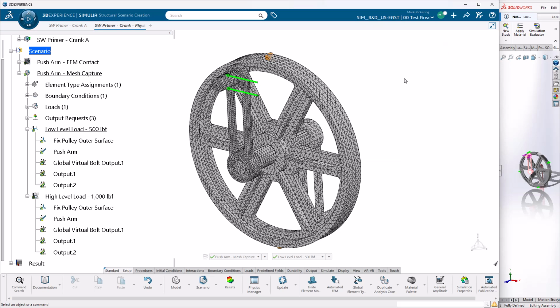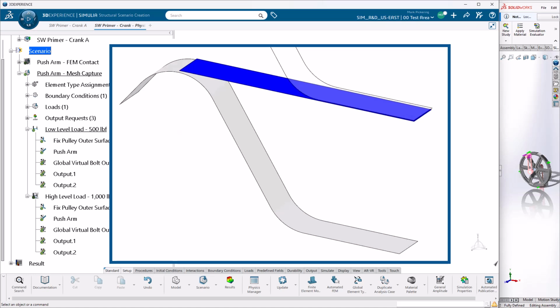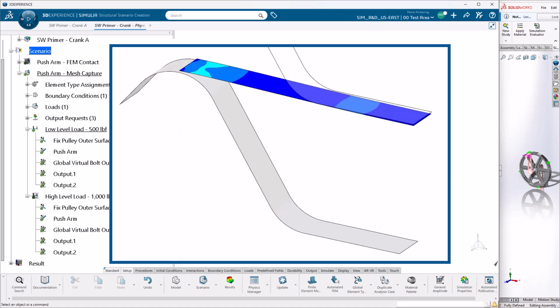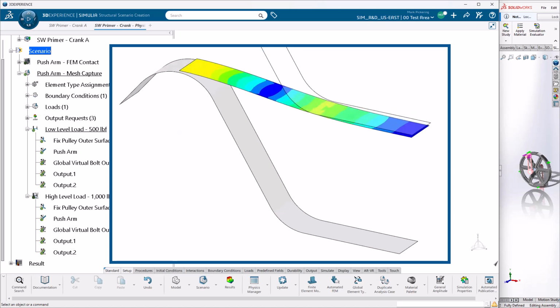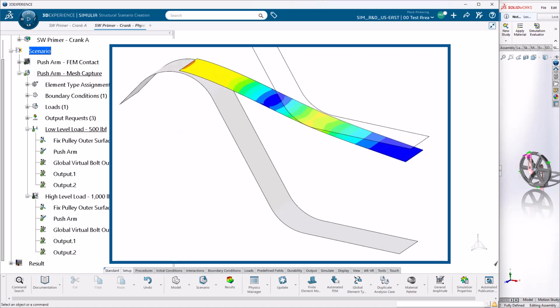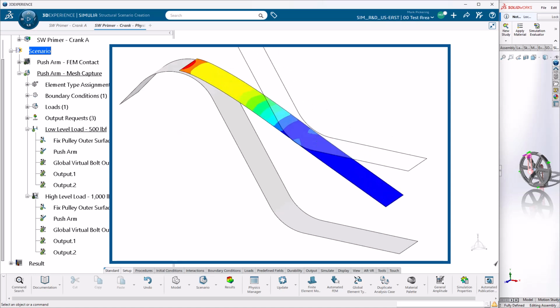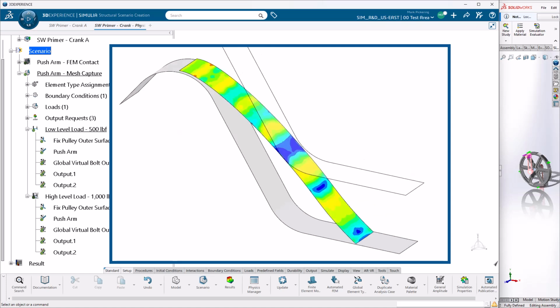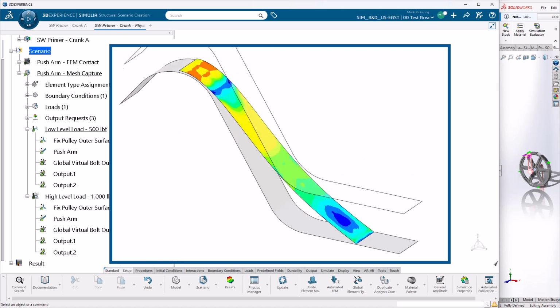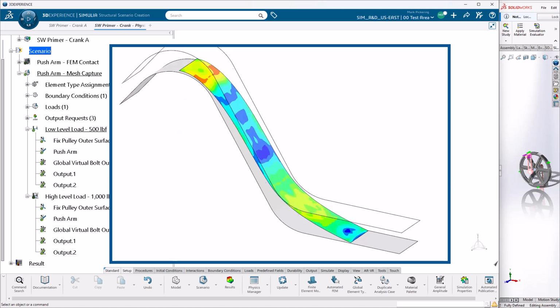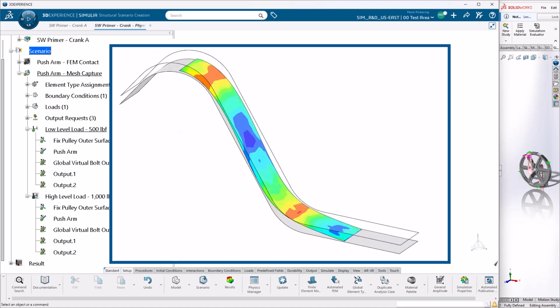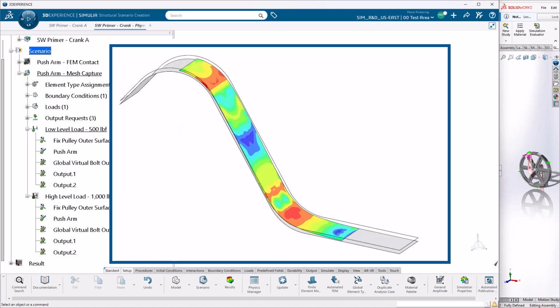One aspect that having multiple analysis cases opens up is sequential loading. In particular, sequential loading involving different solvers. For instance, here we have an explicit analysis, forming a bent strip from an initially flat blank. This is a simple example of common deep drawing, stamping, etc. type processes, where explicit analysis tends to be the most suitable analysis approach, given the potential for significant nonlinear effects.